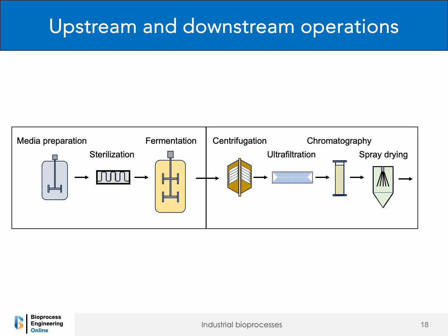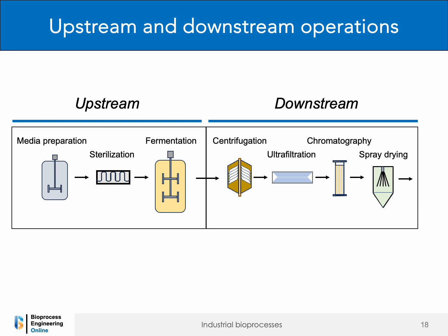In industrially employed bioprocesses aimed at transforming raw materials into bioproducts, a distinction can be made between the upstream and downstream sections of the process. The upstream section encompasses the pretreatment of raw materials, the preparation and sterilization of media, as well as the enzymatic or cellular biotransformation. On the other hand, the downstream section involves operations for the recovery, purification, and ultimately the formulation or drying of bioproducts. The number of downstream operations is contingent upon the level of product purity to be reached.